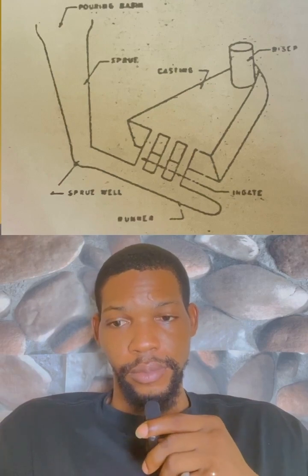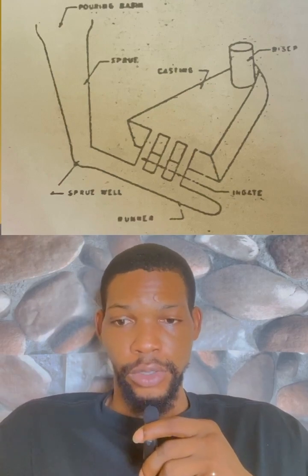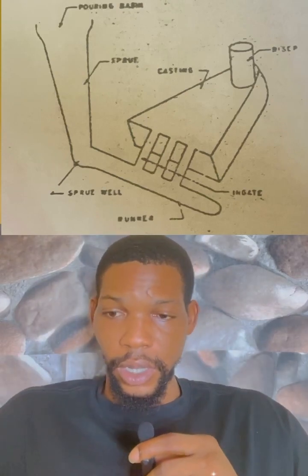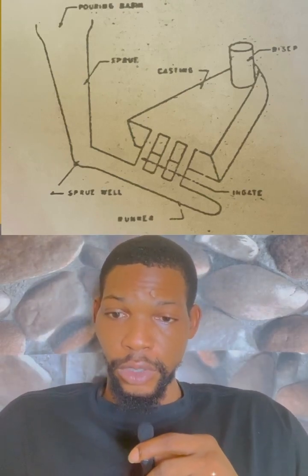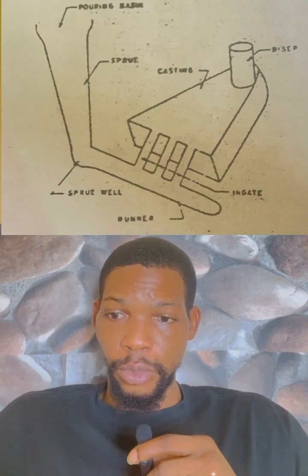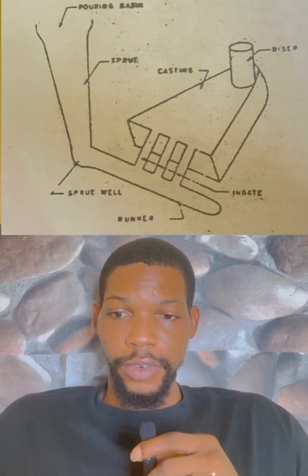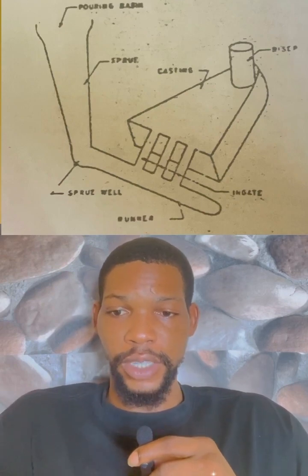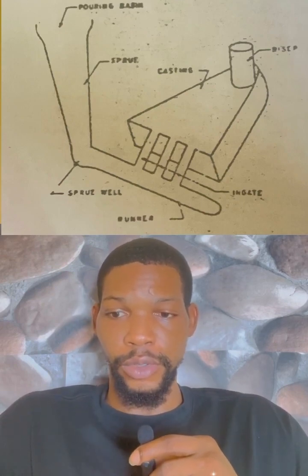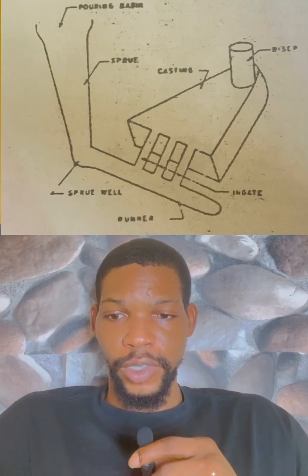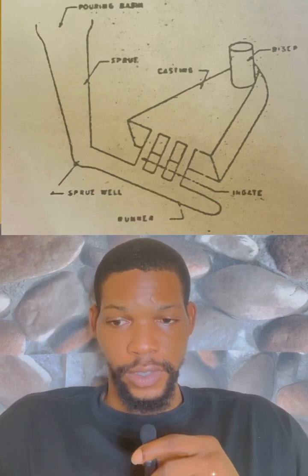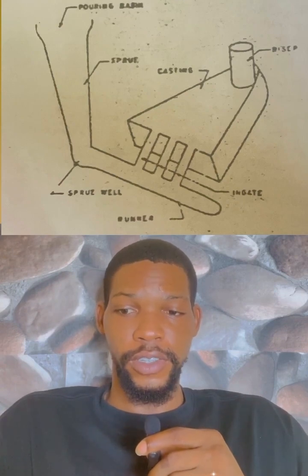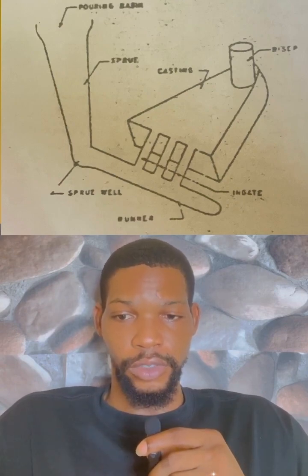This part is made on or in the top of the mold. The molten metal from the ladle is poured into the pouring basin, and from here the metal flows to various parts of the mold. The pouring basin or cup is an important part of the gating system, and the design of this component has been extensively discussed in the literature.